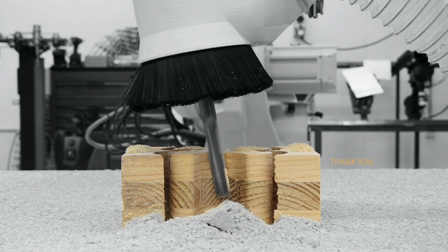The prototyping process highlighted that the key needs to be a perfect fit. Too tight and the joint doesn't come together. Too loose and the joint is weak. Along with this, the prototype showed that the simplicity of the key and the use of wedge shapes creates a stronger joint. Simplicity comes in both design and fabrication.